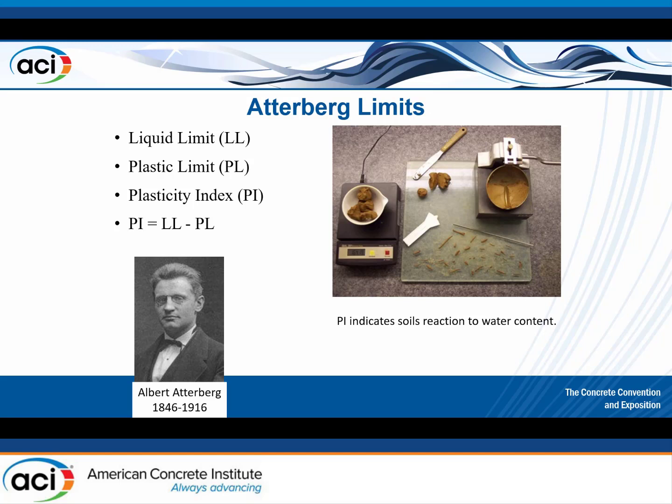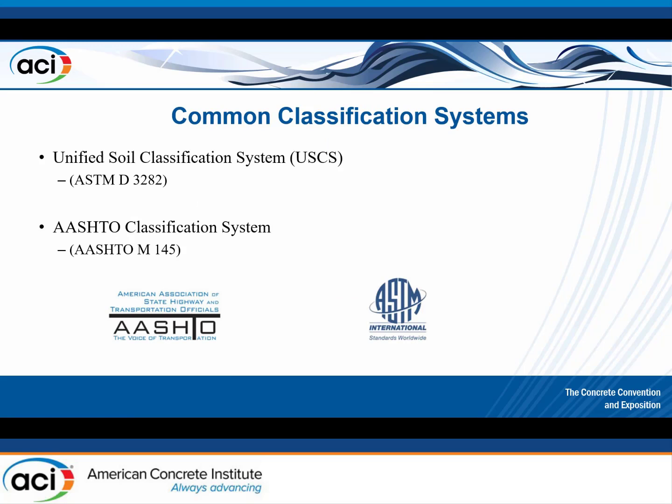And what we have is drought conditions in the summer, so it can form desiccated cracks, large cracks that you'll see. And then when we get to months like October, lots of rain, and you'll see massive expansion of those soils. It takes on that water, holds onto it, and it just expands to get that volume. All right, so that's plasticity.